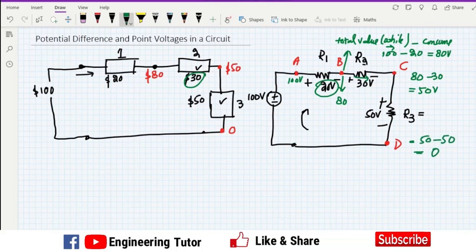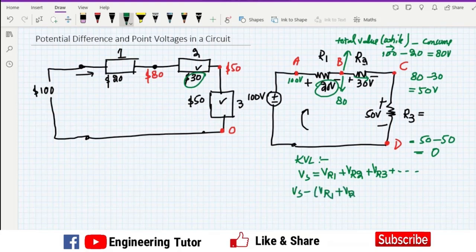We have made this rule. Similarly, the same rule has been applied here by KVL. KVL says that all the voltage which a source has will be consumed across all the circuit elements available in a circuit, and at the end we will have them equal. I mean Vs minus (Vr1 plus Vr2 plus Vr3 up to Vrn) will be equal to 0.